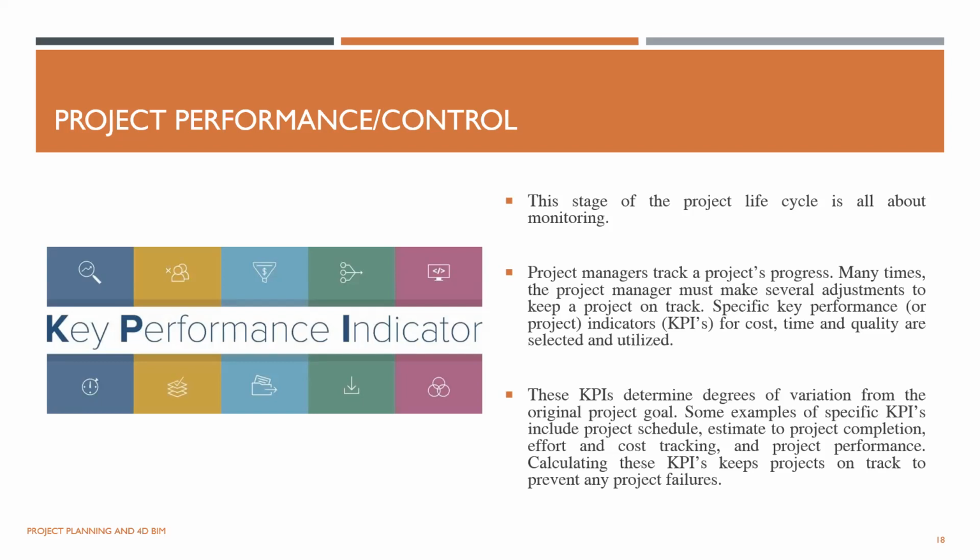If I allocate a project, for example, one month for the completion of the first to second floor, from the floor level to slab level, not only the structural work, but the column reinforcement, formwork, concreting, again the formwork of the slab and reinforcement, concreting, I am allocating 30 days with my maximum resources of 50 laborers, and also steel, rebar and everything I have completed in my plan. Now I'm coming to the actual point of the project.